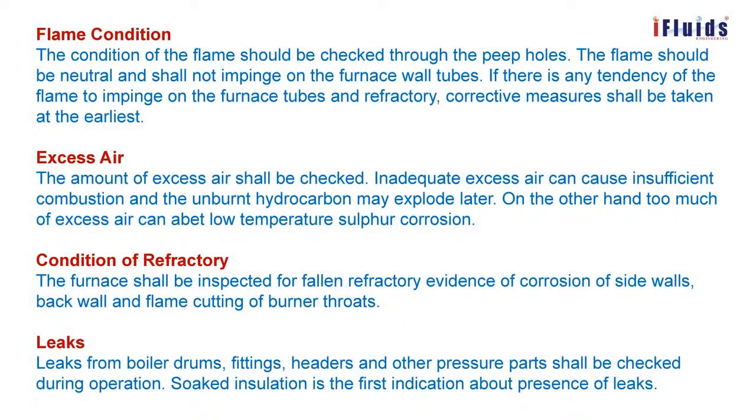The condition of the flame should be checked through the peepholes. The flame should be neutral and shall not impinge on the furnace tube walls. That is very important. Impingement of flame will cause damage in that area, whether it's a tube or a combustion zone. Wherever the flame touches the body, there it will get damaged.